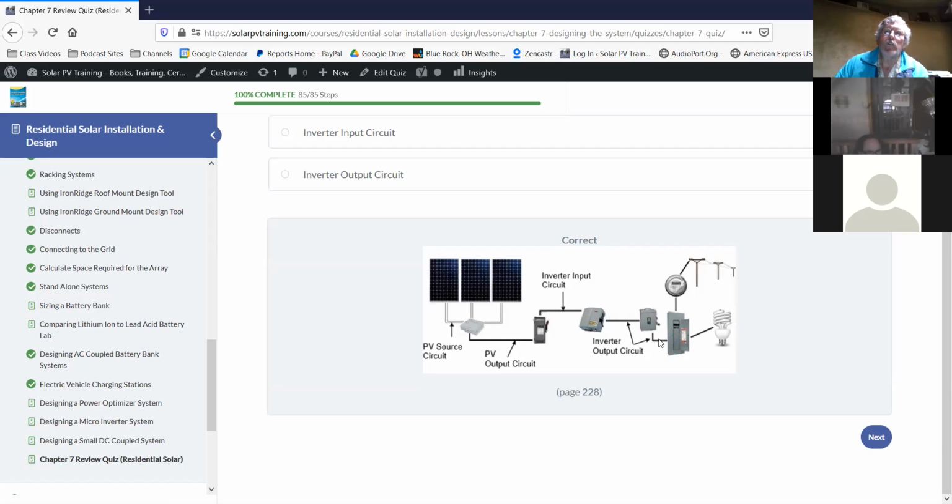So the purpose for those requirements is if a first responder comes to the house, or let's say your utility company comes to the house and wants to shut off the service, often the very first thing they're going to do is pull the electric meter. So they're going to come to the electric meter and they're going to see a label that says, warning, this home or this building has a secondary power source. Often the label will say a PV system, but it will say it has a secondary power source, which basically tells them pulling the meter may not be enough.